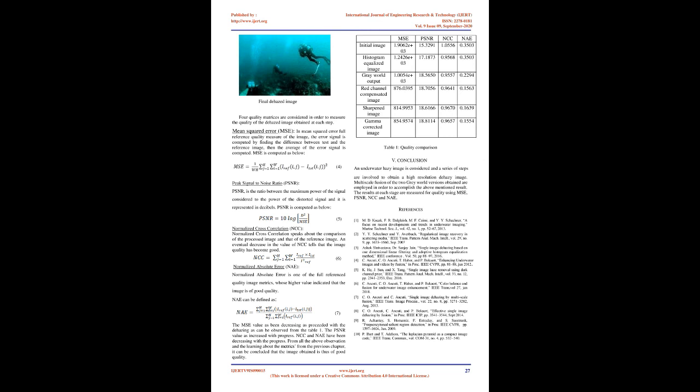Sharpened version. Laplacian pyramid of sharpened image. On application of the classic white balance, the gray world algorithm, there is a better visibility in the so obtained image as compared to the hazy image that had been considered initially. But on application of the gray world algorithm, though the image gave a better quality, red artifacts have come into the picture. Now there is a necessity to compensate for this red artifact that has been encountered, since red color, being of longer wavelength, gets lost first while traveling through the water.